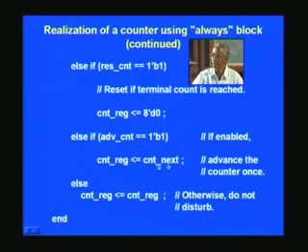So we have already pre-incremented earlier using the assign statement, and now the clock will come only after a delay, because clock strikes periodically at one particular point. At that point when it does, whatever was the pre-incremented value will be merely pushed into this counter register. Another alternative way was to dispense with that assign statement there, and thereby remove one signal. We are unnecessarily introducing one signal, but with the aim of increasing the speed of processing. So that's a good habit.